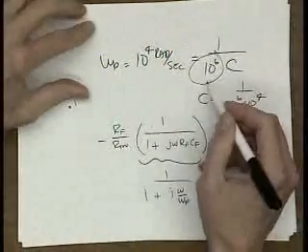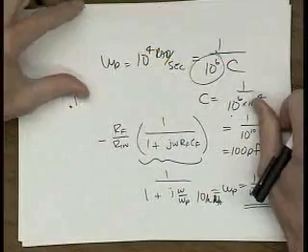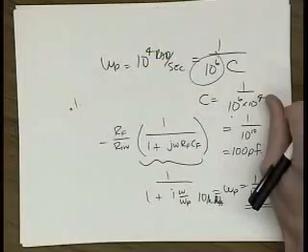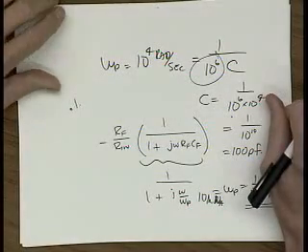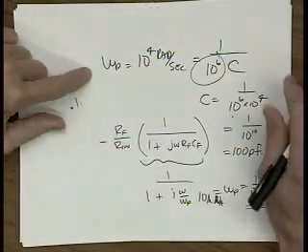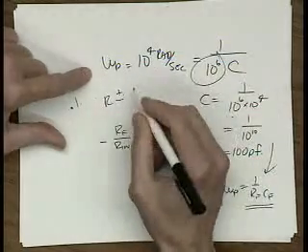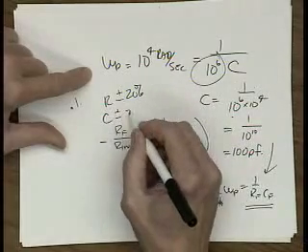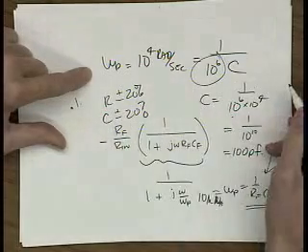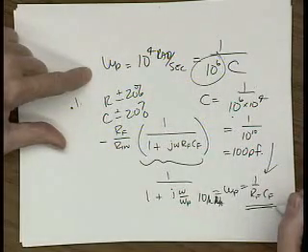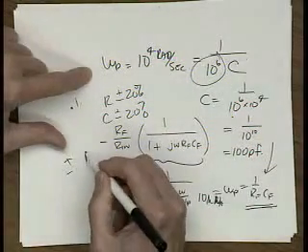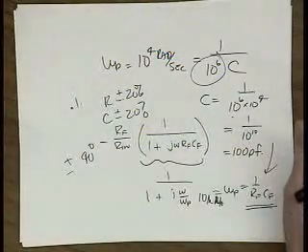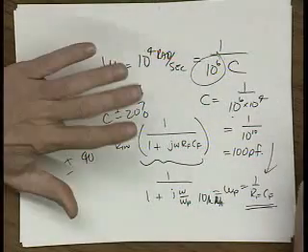And a megohm resistor is not great either. What's another problem? So area is a big problem. What's another problem? How about accuracy? If that resistor is plus or minus, let's say, 20%, and the capacitor is plus or minus 20%, what's your corner frequency? Plus or minus like 40%. So not only did you use up a whole chip, you didn't even get the right answer.